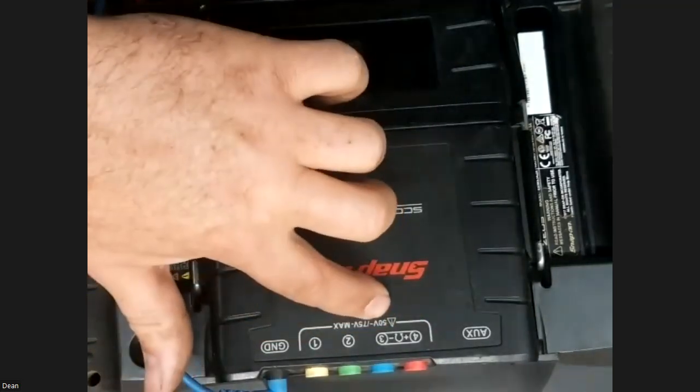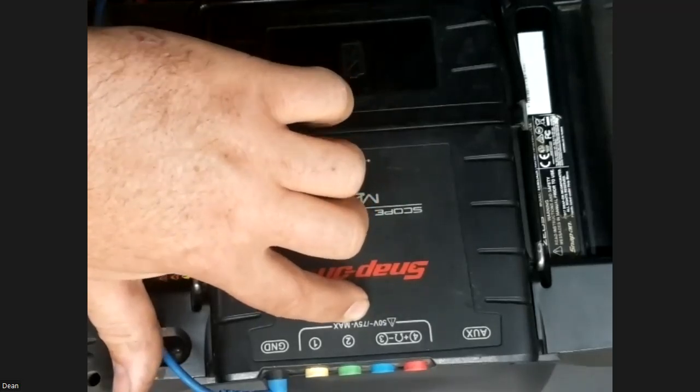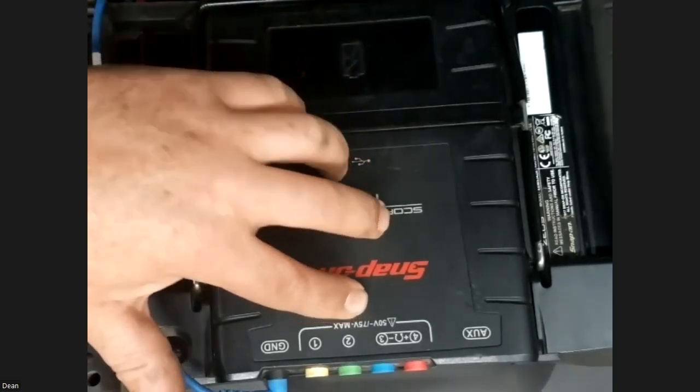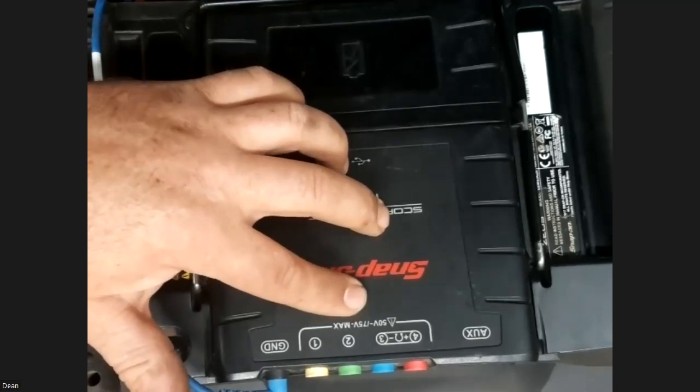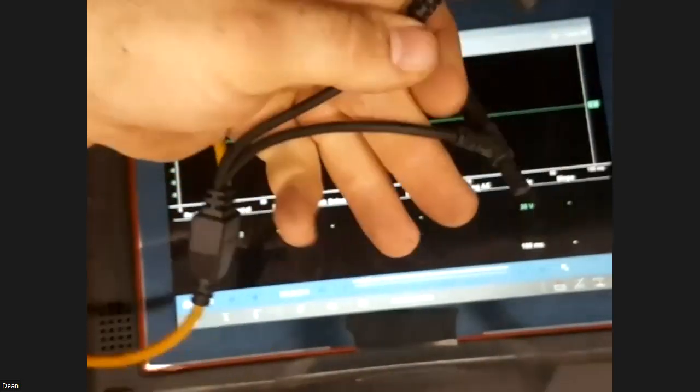Besides that, these are all checked. Make sure you look at the limits: 50 volts and 70 volts, 75 volts max. You need to know what your scopes can handle. That's why certain scope leads will have grounds off of them. If anybody else is using these type of scopes in the field, like Snap-on, the other thing you need to know about setting up your scope here is you're going to have two grounds, right? These two grounds, one ground and an X ground.